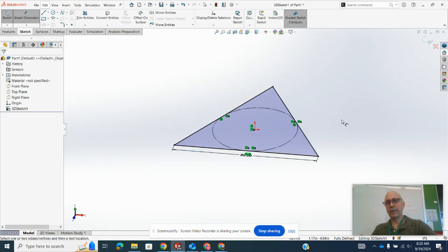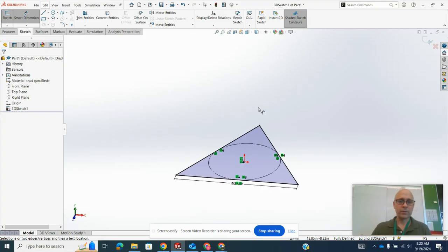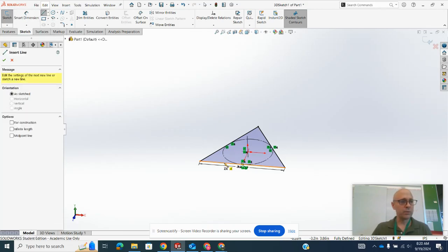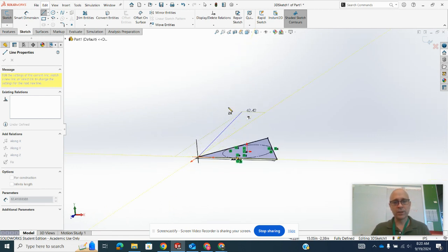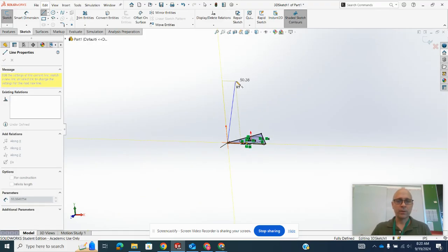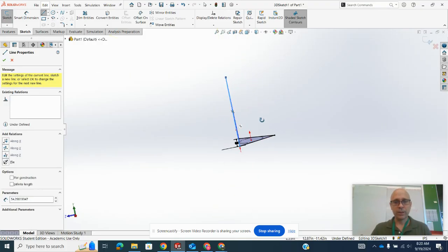Okay, but I'm not done yet. So next thing I'm going to do is, I have this face. I'm going to start sketching these legs that meet up at a point at the top. I'm going to create 3 of those 6 elongated surfaces. If I just start sketching, it's going to kind of stay in this plane. So I want to hit tab and choose a plane that's more vertical. I'm going to move this out of that plane. We can't stay in that plane, but I can do that later.